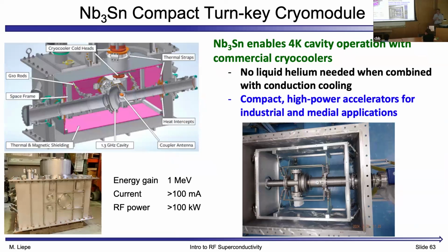And finally, we thought about applications of these. So here is the conduction cooled cryomodule. On the left is the design, with the single cell cavity sitting in there, cooled from the top with cryocoolers. There's no liquid helium, no liquid nitrogen involved whatsoever. It's all just cooled via thermal conduction. That is how the cryomodule looks in here.